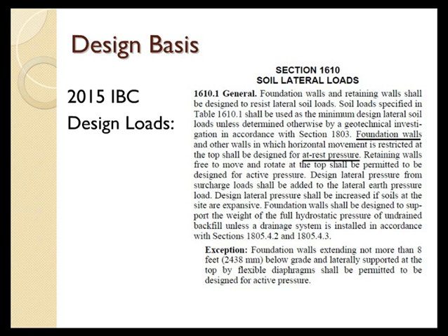If we have situations where our foundation walls are supported top and bottom, the IBC would require that in these situations we design for the at-rest design pressures. In cases where we have retaining walls or other types of structures that are not supported at the top, then we're generally permitted to be designing for active pressures. These are the reduced pressures, that is the shear strength of the soil begins to be engaged, relying upon less wall to resist some of those lateral loads.